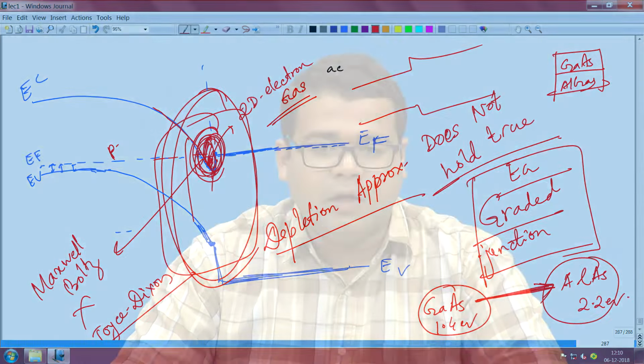We have talked about heterojunctions and heterostructures. We introduced the band diagram concept, the PN junction and other things, and how the band alignments are there. I hope you are now familiar with heterojunction band diagrams. There can be different alignments, different dopings, different band gaps and band alignments. So depending on that, you have to think and draw the band diagram. It can be PP, it can be NN, NP, PN, and wide and narrow. They can have different combinations, and you remember the straddling, staggered, and broken gap alignments depending on the electron affinity. So when you are given a new heterojunction to make, on both sides you just do that thing.